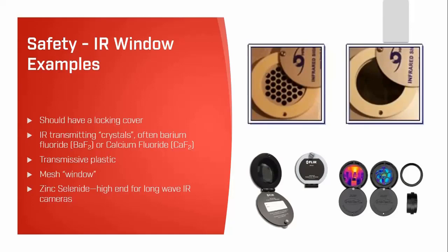Commercially supplied infrared windows will have a cover that should be in place when not being used, and the cover also provides protection for the window to keep it clean and dry and out of harm's way. An excellent additional benefit of using infrared windows is that you will do your surveys not only safer but faster, and you won't be bothered with defeating the interlocks, as we've said on previous pages. Be certain that the device is UL rated and listed for the purpose, and remember that you need to compensate your reading, as an IR window isn't 100% transmissive. If you're unsure of this, it may mean you need to attend a training course.